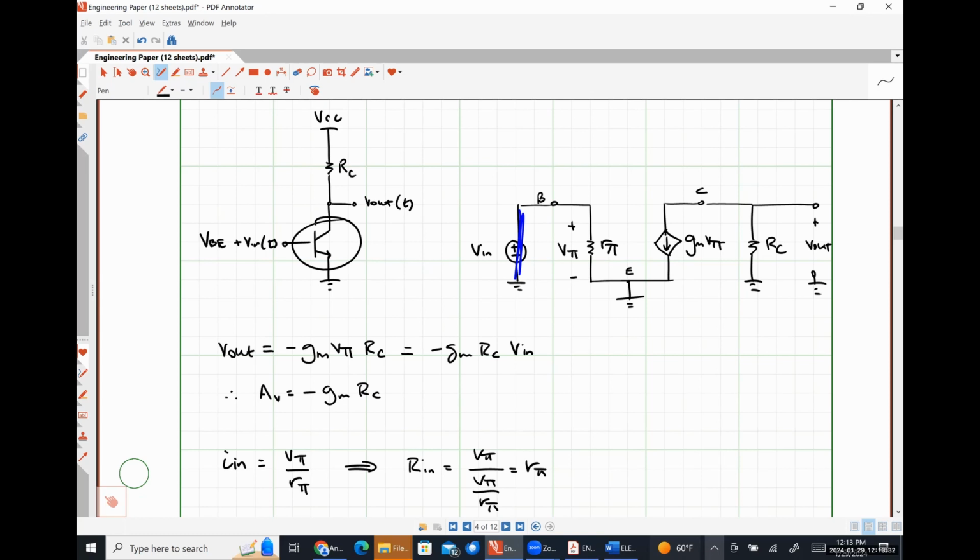So we are only going to bother with analyzing BJT amplifiers because effectively, if we take the limit of our BJT amplifier as we let R pi approach infinity, it's the exact same thing as doing a MOSFET. So we're going to spend 95% of our time looking at BJTs and then ask what this looks like when R pi is infinity, and then just use that for our MOSFET relationship. There's no reason to analyze the circuit again. It's the same thing. All right, I'm done.